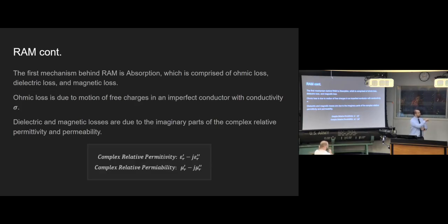But in the case of things like this, there's a concept. Everyone knows resistance, but resistance is actually just a part of something called impedance. And impedance is built out of resistance, and then it's built out of what's called reactance. So there's resistance and reactance. Reactance is like, think of it as the resistance of a capacitor or an inductor, which is basically the resistance of an electric field and a magnetic field. These things are real goofy, and there's a reason RF engineers make so much money, because it's horrible to deal with. But there's a pretty intuitive explanation for how this goes.